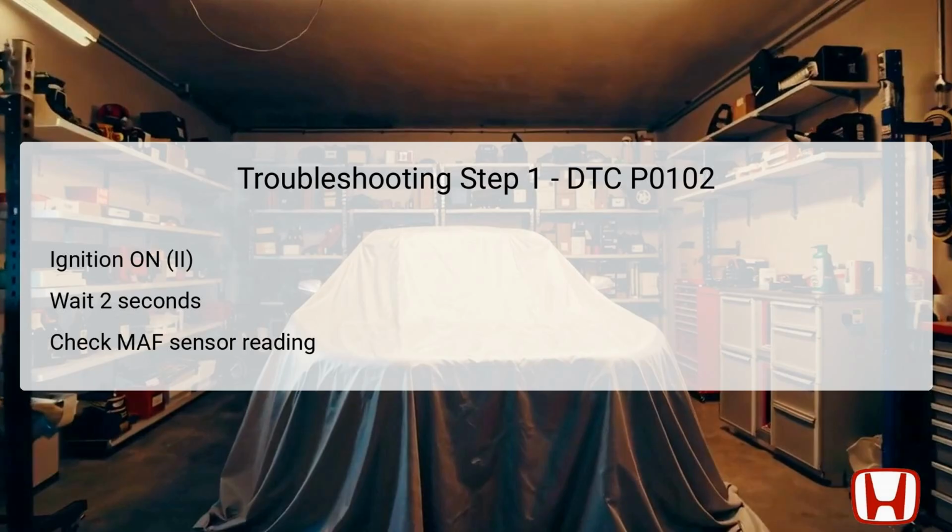If a normal reading is observed, it suggests a transient or intermittent failure, and the system may be operating effectively at that moment. At this juncture, it is also wise to inspect for poor connections or loose terminals at both the MAF IAT sensors and the ECM.